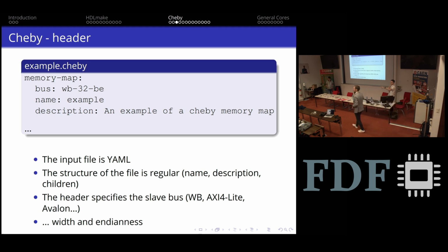One last question. Thanks. On this slide, you list a couple of slave buses. Is there any support for IPbus, which is pretty well used? If I'm not wrong, IPbus is something you send over Ethernet. No, it can run over PCIe and many other interfaces.